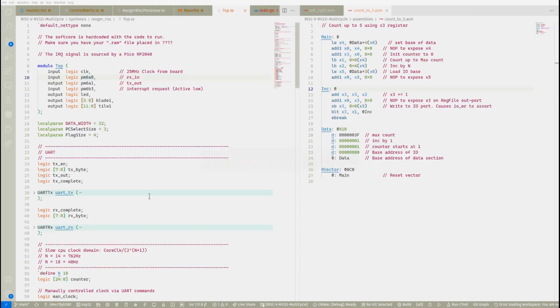The next issue, which really isn't an issue, is something I kind of knew about, but I forgot because I hadn't done synthesis in a while. If you don't take any of your components and route them to somewhere out in the physical world, your toolchain has a really strong chance of logically reducing all of your components to zero. So even though it synthesized, which is nothing more than just syntactically and structurally checking your code, nothing comes out. Your resource allocation will be almost zero.